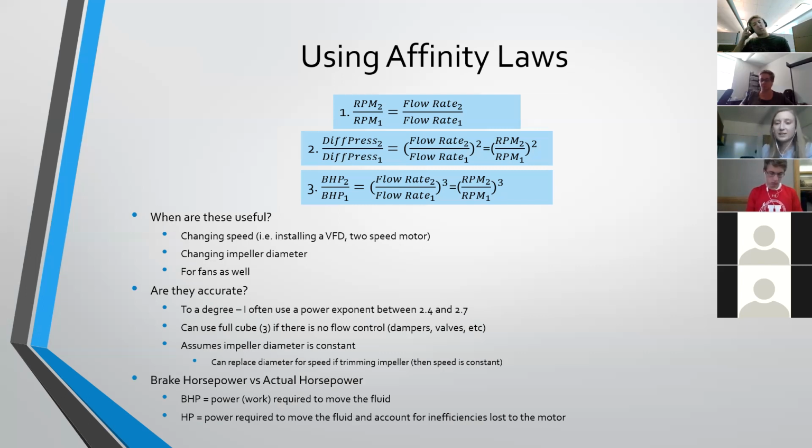But since normal pumps and fans have dampers and valves, that power exponent isn't quite correct. So we use an adjustment factor, between 2.4 and 2.7, and you can determine what you think is best for your situation. That should help you be a little more accurate.